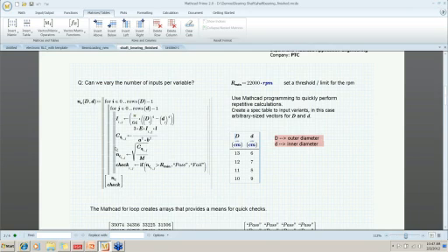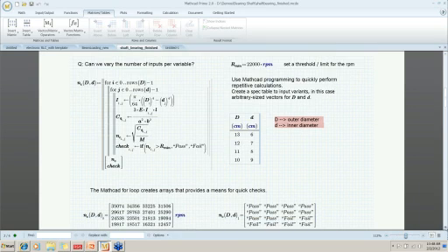In this Mathcad inline program, we have 2 for loops that are basically looping over all of the outer diameters, all of the inner diameters, and performing this calculation, and then checking it to see if it satisfies a requirement for the minimum shaft speed. Here's a very straightforward if statement that says if our shaft speed is greater than the minimum, then we pass, otherwise we fail. We're going to return the shaft speed for all of these combinations for outer and inner diameter. So we'll have 16 results and 16 pass-fail results.